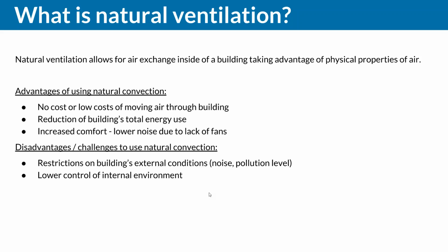It can also include other things like noise and pollution level. Let's say you have the perfect flow conditions and the design of your building is really good for natural ventilation, but you have a highway on the other side of the road, or some facilities releasing a lot of pollution. This can be a big problem, and it can end in the fact that you are not able to use natural ventilation.